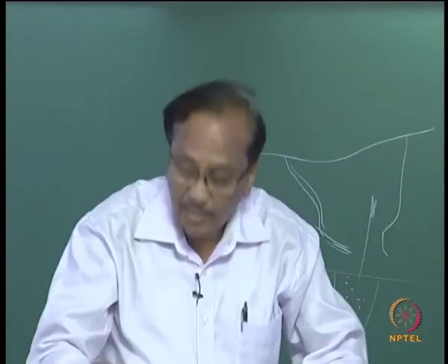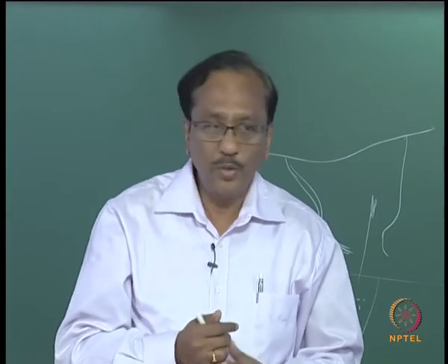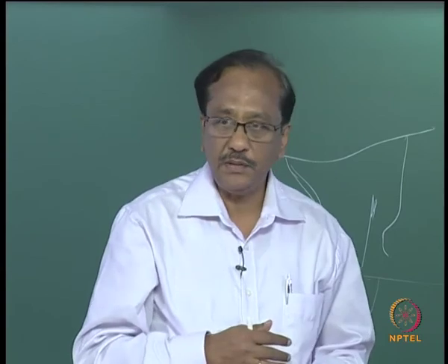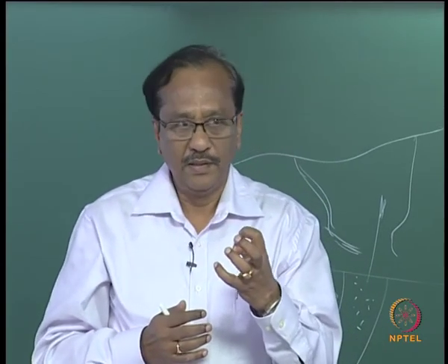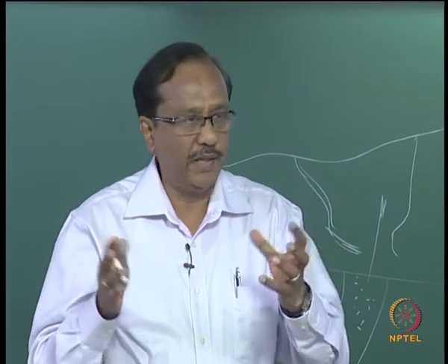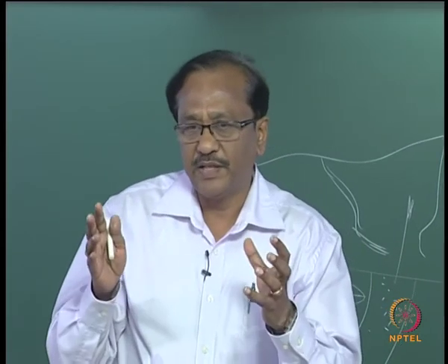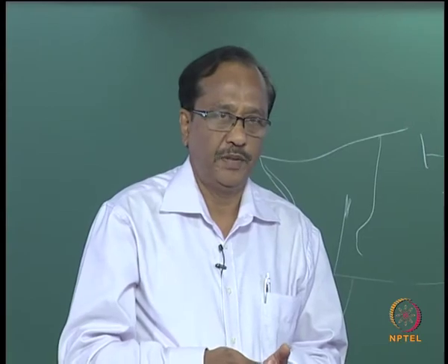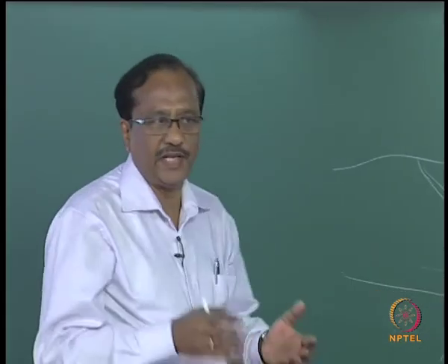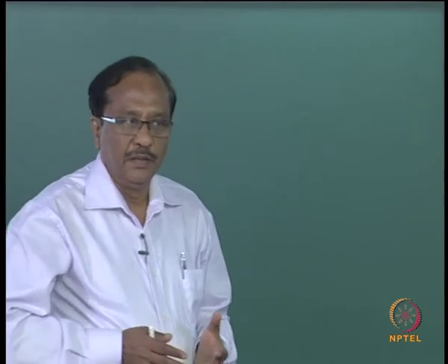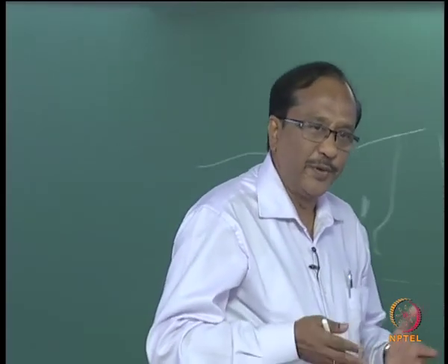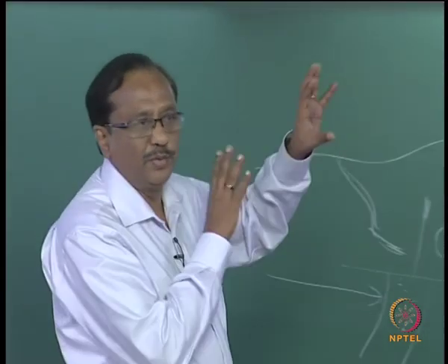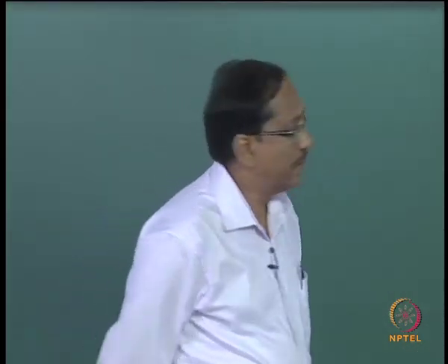You want the sand to deposit and you do not want the sand to move away. So you would like to have coarser sand; such areas could be developed in areas characterized by coarse sediments. So whether it is fine or coarse, both have advantages and disadvantages, but it is extremely important to know the characteristics of the sediments.